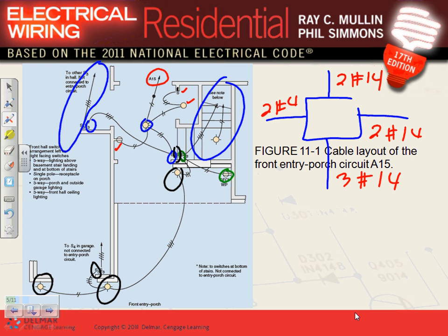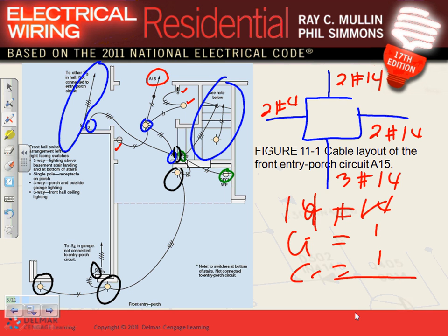Yeah, you'd have to take something else. They have 9 conductors, number 14. Well, you've got to have a clamp, and a ground, so that will get you 9 number 14 plus a ground. Internal clamps, that will get you another one. So 9, they'll give you 11. Should be able to fit. Still number 14, 11 of them.